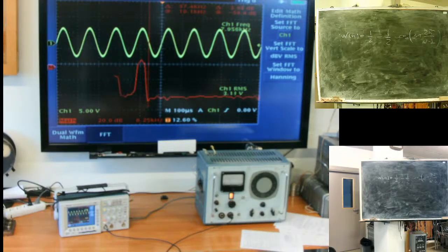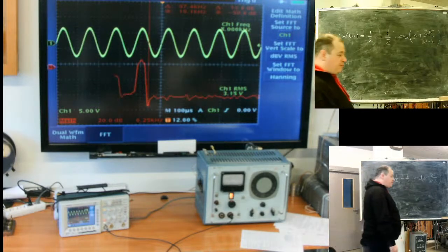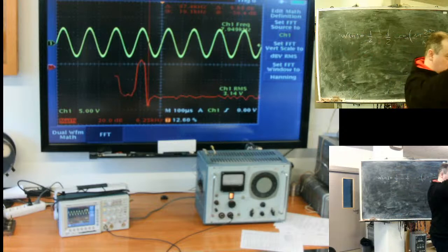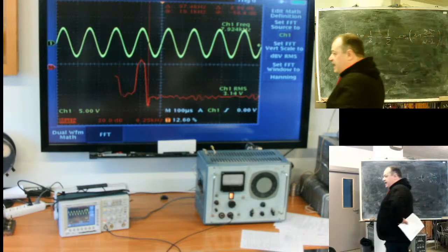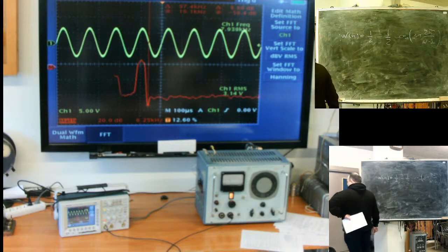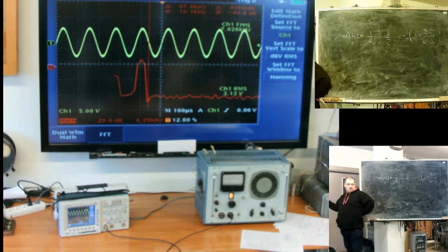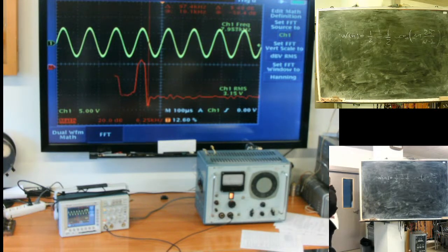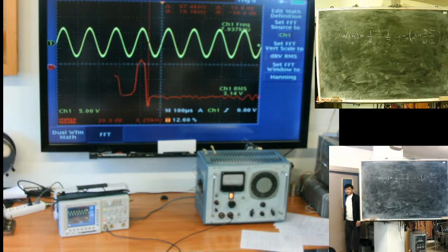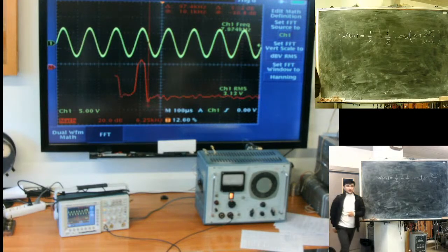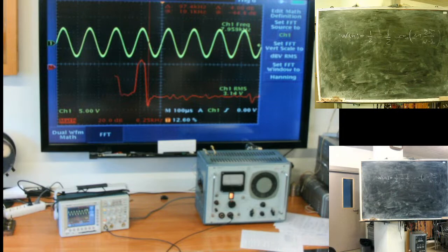We do not perform a Fourier transform for the whole signal. We perform it only for some cutoff of the original. We can mitigate problems caused by this limited observation time by selecting an observation window without sharp change on the edges.